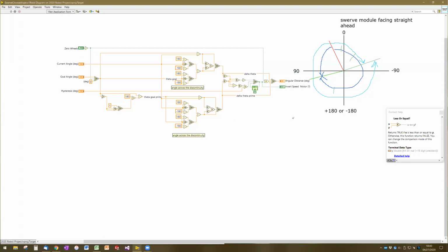But if you're above 5 feet per second, if you're already going fast, then I don't want you to switch into low gear until you get down to 2 feet per second. And so you end up with this zone where the decision that it makes is different based on what side of the zone it's on. And so it avoids this sort of oscillation behavior.